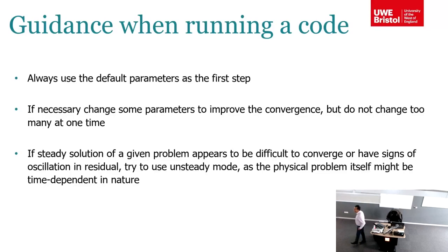If it doesn't converge, switch to unsteady mode. If your steady mode solution doesn't converge, switch to unsteady mode and run for some time, get an answer, and then you can use it as a starting point for the steady solution. Again, those are tricks that you can do.